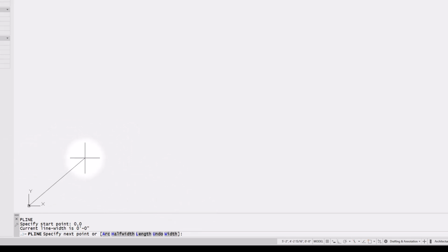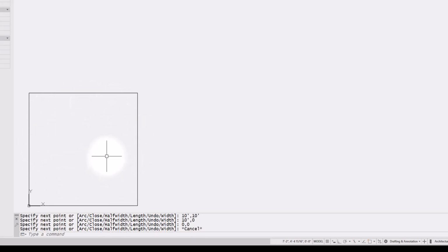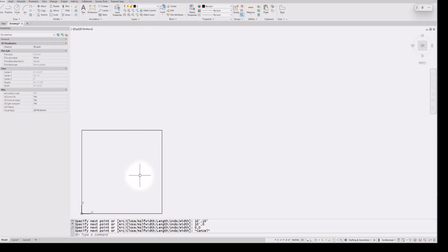Next, we're going to start working on drawing just using the keyboard. So we're going to hit 0, 10, and now we're going to use the feet and Enter. And now we're going to go 10 feet, 10 feet, and Enter. And now we can go 10 feet, 0. And then finally we'll return to 0, 0. Enter. So now we have drawn a box. I'm going to hit Escape to get out of that command. So that's a real efficient and accurate way to draw a box.